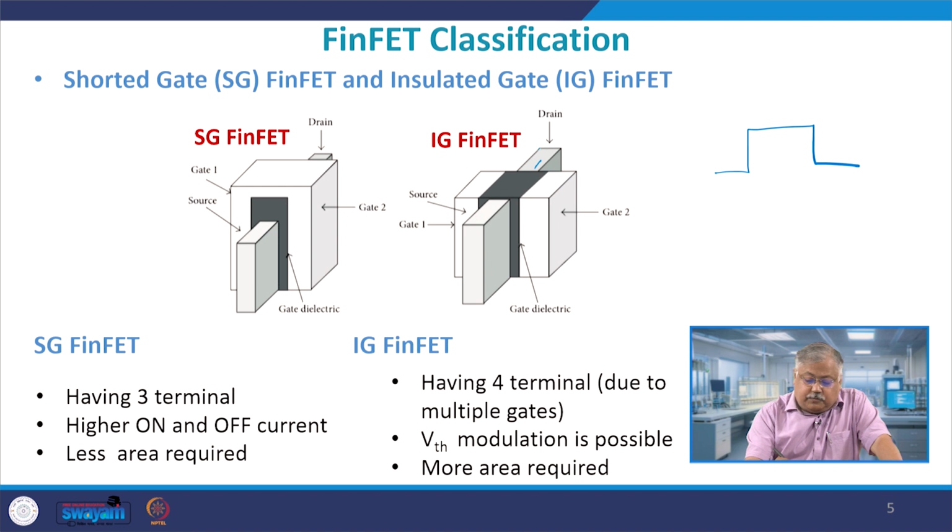Suppose your source drain starts from here, this is your extension region, and your source starts from this extension region. What you can do is you can actually do an oxide growth here, maybe you can do an HfO2, hafnium oxide, or even titanium oxide spacers, right.